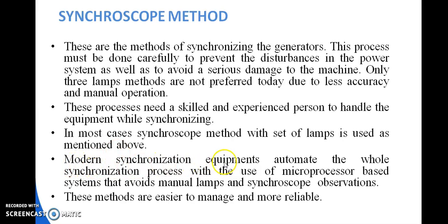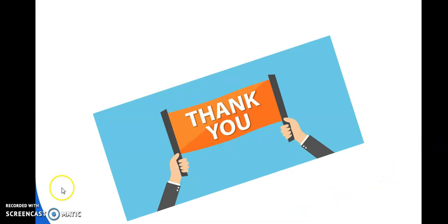Modern synchronization equipment automates the whole synchronization process with the use of a microprocessor-based system that avoids manual lamp and synchroscope observation, and these methods are much easier to manage and more reliable. That is why today we are going forward for using these microprocessors.